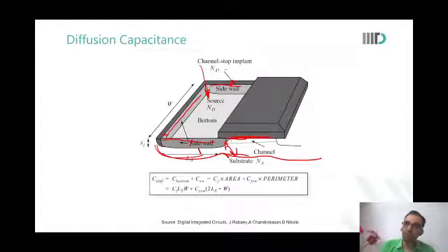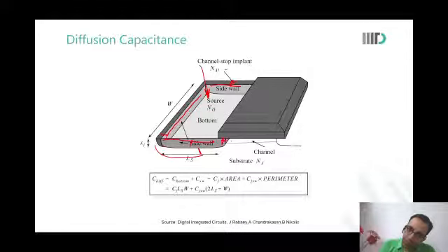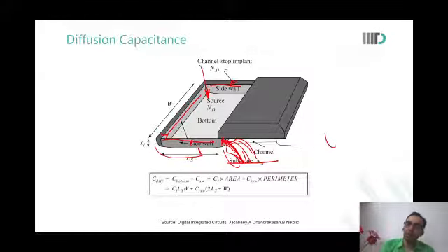In fact, there is an easier way to flow charge from the inversion layer, in so many places. So is it becoming negligible because it is too far? Capacitance of this part of the plate to this part of the plate is such a big, long path. The dielectric thickness, let us say T depth, is so long that the capacitance is insignificant in comparison to what you will see over here. Okay.